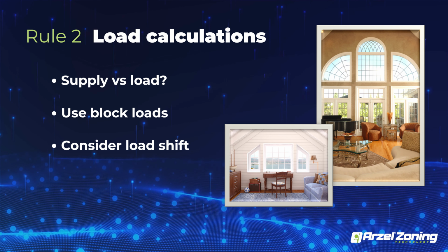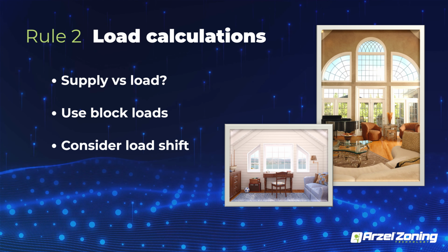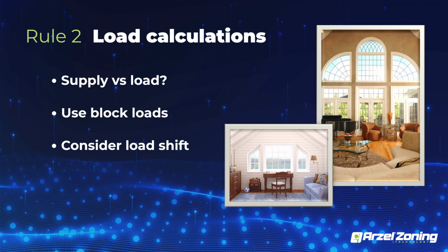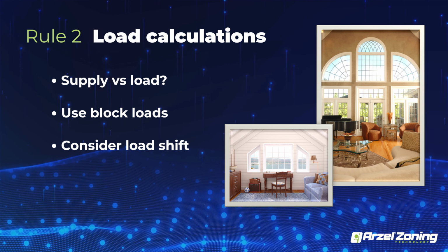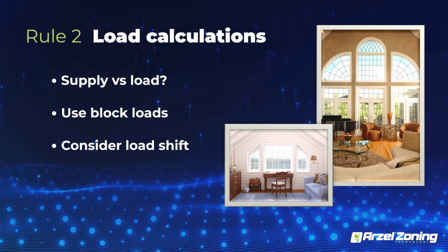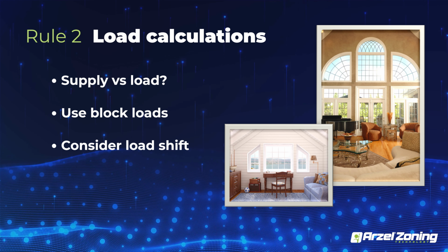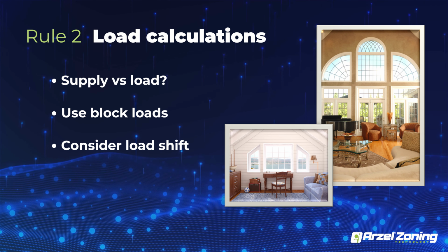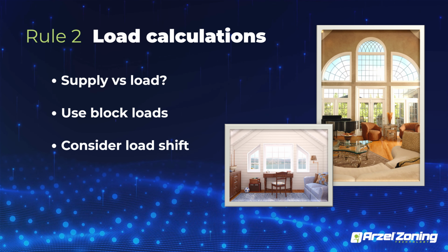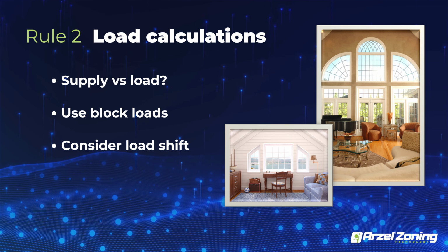Do I have 3 tons of air conditioning and only 2 tons of ductwork? Do I have rooms without enough supplies? Are there inherent design issues? Some of that, for some of you that have been doing it long enough, you can probably get a pretty good feel for by just eyeballing. If you don't have that kind of experience, maybe just measure the ductwork, get your ductulator out, and see if you have enough. Does it match my equipment tonnage? Just do some basic evaluation: look at the rooms, is there enough supply, those kinds of things.